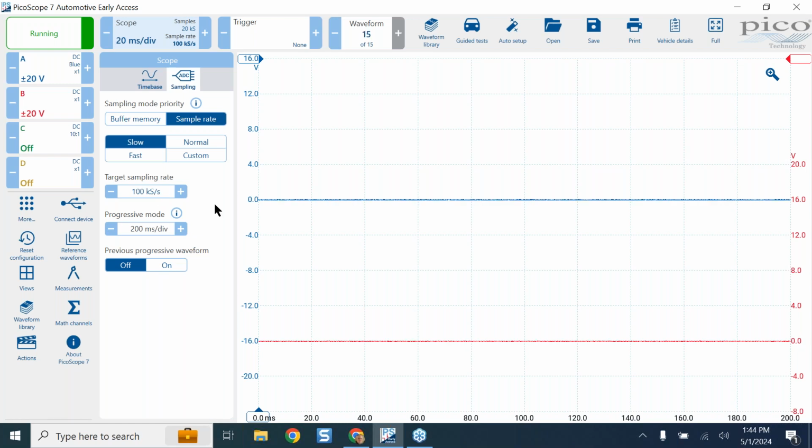It's going to give you 100,000 samples a second. That's pretty low. That's less dots on that screen, obviously. If I do normal, we selected 2 million samples. Personally, I use 1, but that's just the vote. I was outvoted by 1, so we went to 2 million samples. You can use fast as well. Not a lot of signals right yet that you'd be using anything that high at 80 million samples per second.